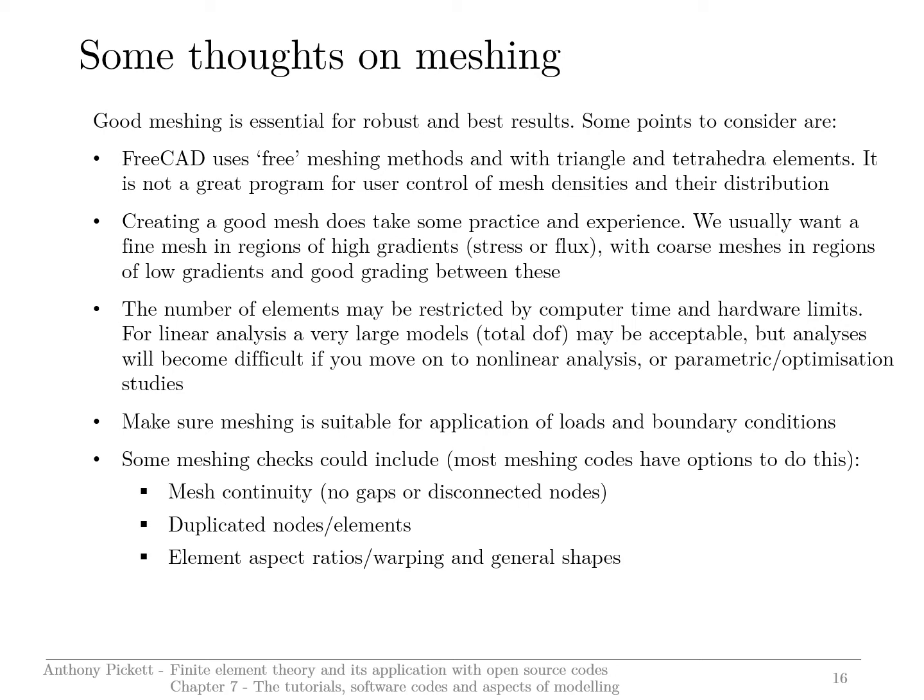In principle, if we think of a mechanical problem, what you're trying to do is have a fine mesh in areas of high stresses, and you can use a somewhat coarser mesh in areas of low stresses. Or more correctly, you're looking for a fine mesh in the areas where you have high stress gradients. The same applies if you're doing a field problem with flux. You'll need a fine mesh in areas where there's a lot of flow or gradients of flow taking place, and you can use a coarser mesh in other areas.